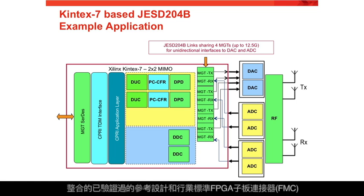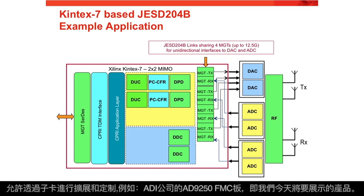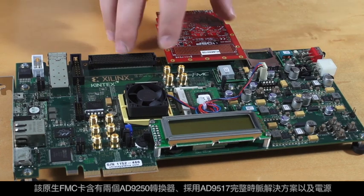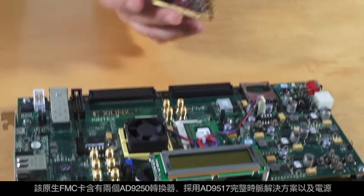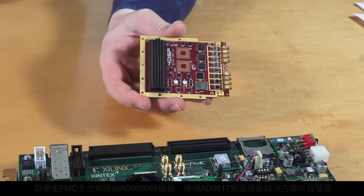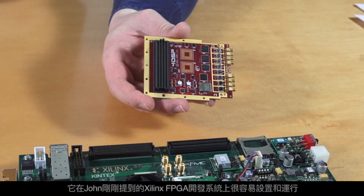The included pre-verified reference designs and industry-standard FPGA mezzanine connectors, FMC, allow scaling and customization with daughter cards such as the Analog Devices AD9250 FMC board, which we are going to show today. For high-speed ADCs, the JESD204B interface is a high-speed successor to LVDS and CMOS interfaces. This native FMC card contains two AD9250 converters, complete clock solutions using the AD9517, and power, and it's easy to get set up and running on the Xilinx FPGA development system John just described.